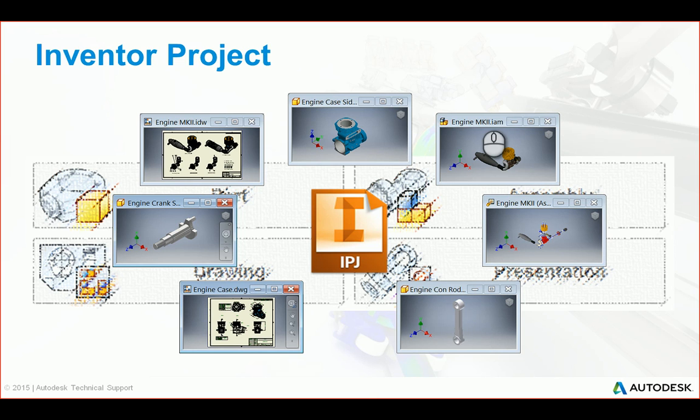So we tell it where the design library, the design data is, and this is all your styles. It tells it where your templates are, where your content center files are to be stored, and it tells Inventor these are locations of our libraries and frequently accessed folders.